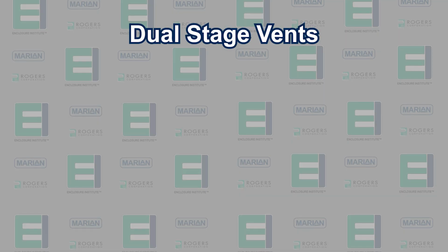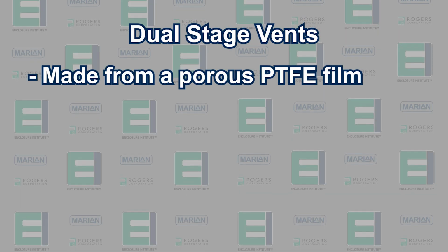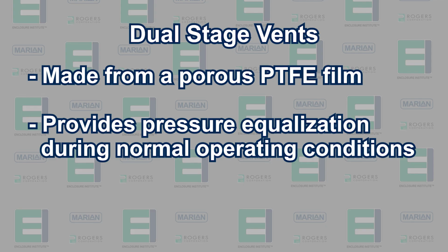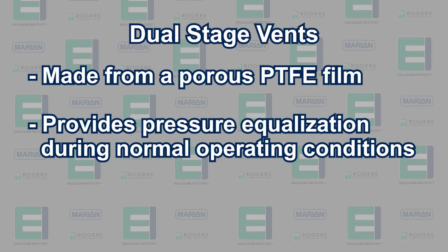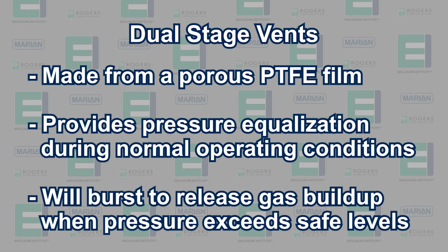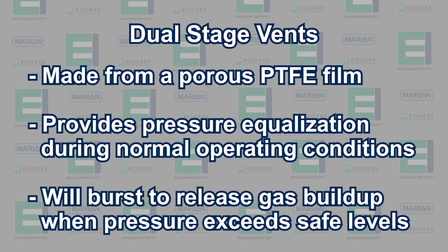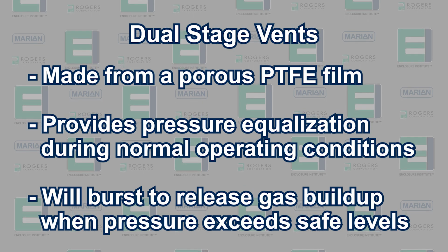A dual-stage vent is a combination of both. Typically made from a porous PTFE film, this type of vent provides pressure equalization during normal operating conditions, but will burst open to release the dangerous buildup of gases when the pressures exceed safe levels.